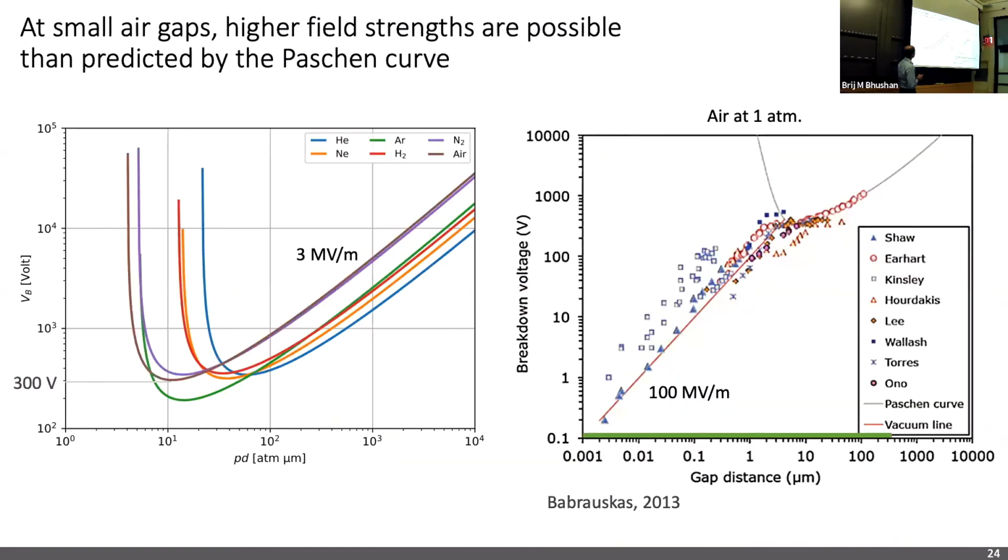Okay, so dielectric discharge. Normally in air, the quoted electric field strength is 3 megavolts per meter. And this comes from the studies done by Paschen, also known as the Paschen curve, wherein the x-axis here is a product of pressure and displacement. So this is studying at what voltage breakdown occurs as I vary the gap or I vary the pressure of the medium.